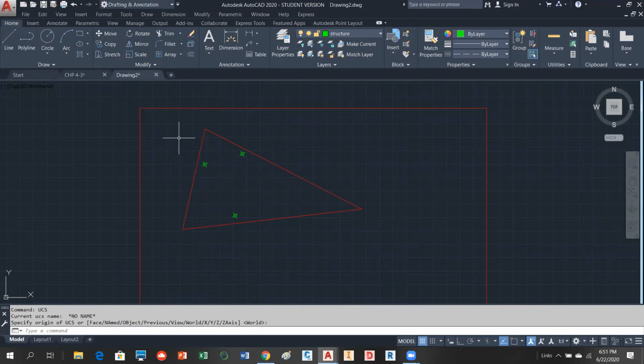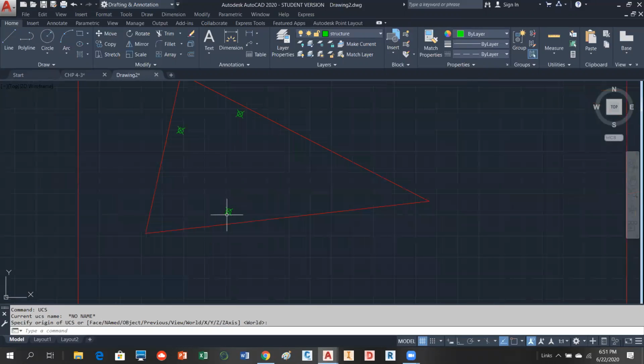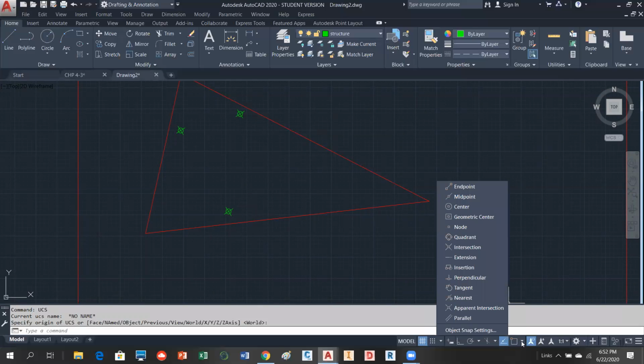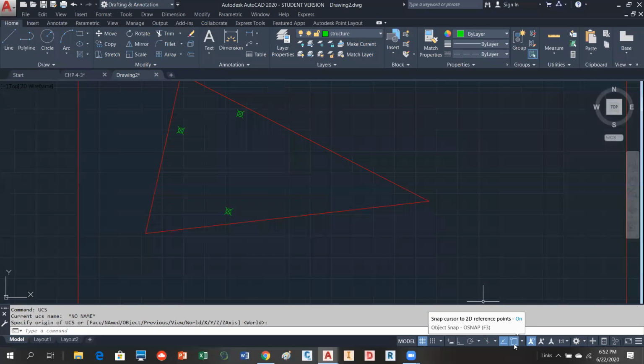And we are now ready to set our tank. So the tank is going to be a 3-point circle that's going to come through these 3 points. And so I'm going to go into my OSNAPs, and I'm going to set the OSNAP current to what's called a node OSNAP. This will just make it simple. And make sure that it turns on.